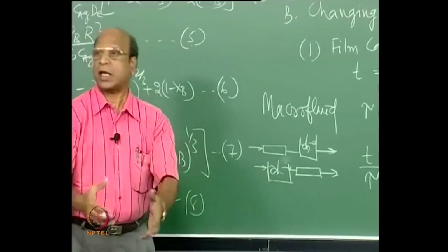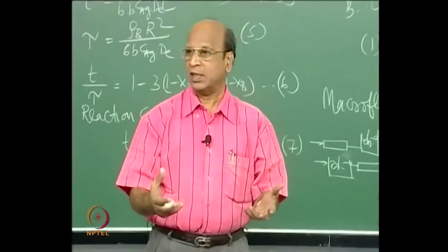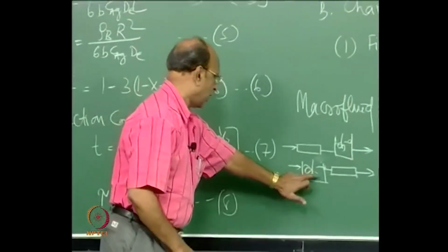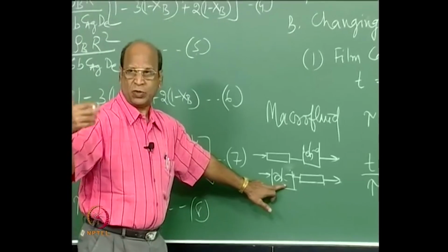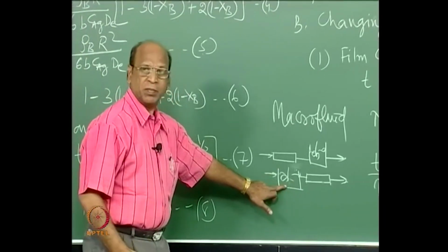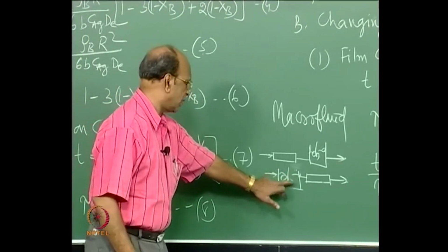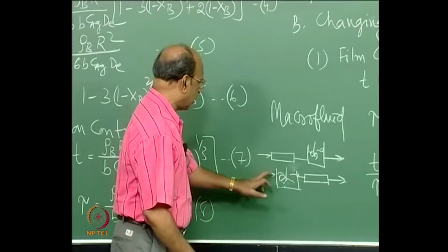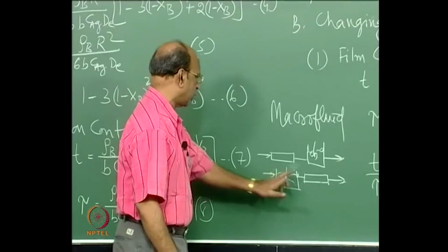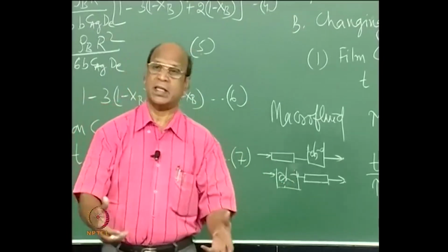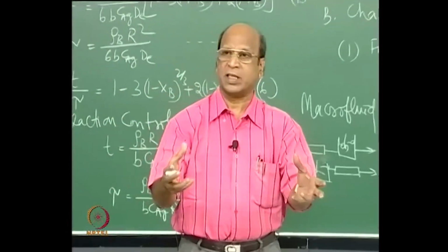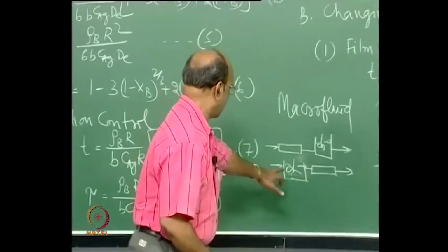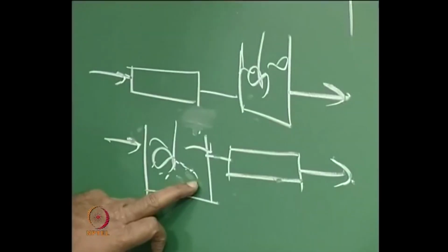Whereas here, if I conduct the same second order reaction, it gives me low conversion, because at the first instant itself you have the concentration decreased because of perfect mixing. The idea here is, when fresh concentration Ca0 is just put inside, it mixes with the already continuously flowing stream where reaction is continuously taking place.